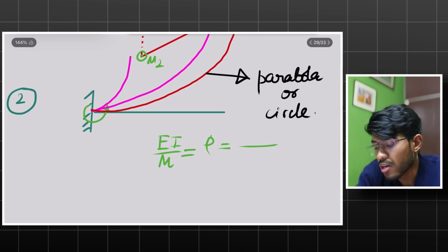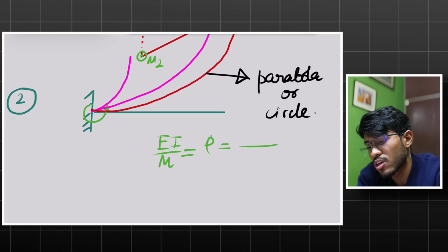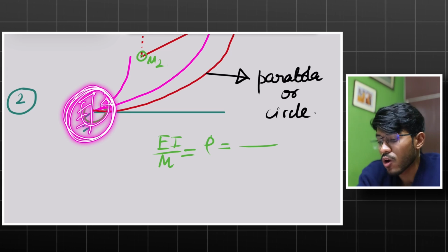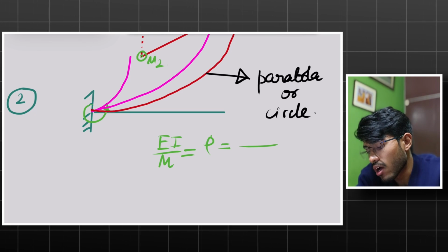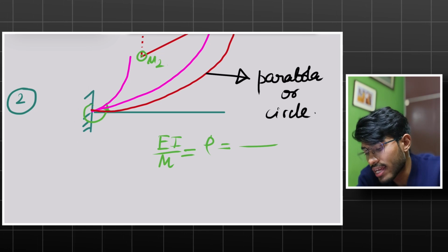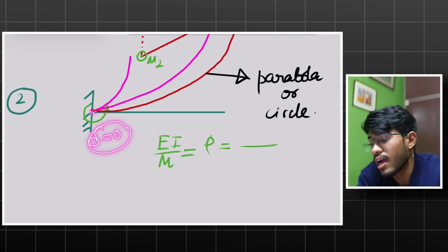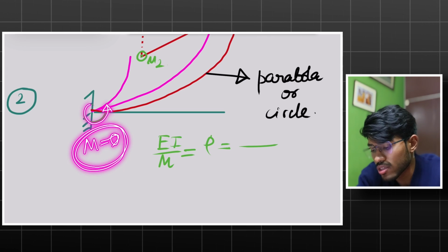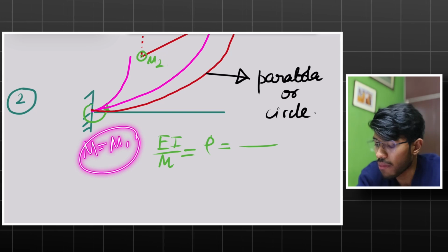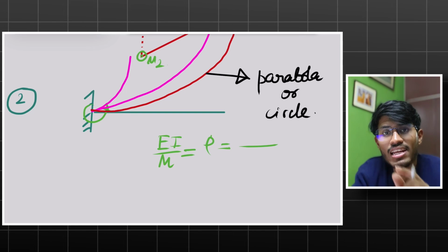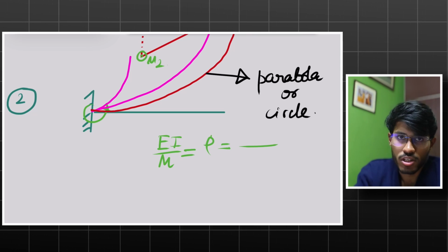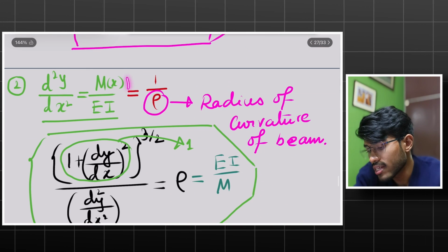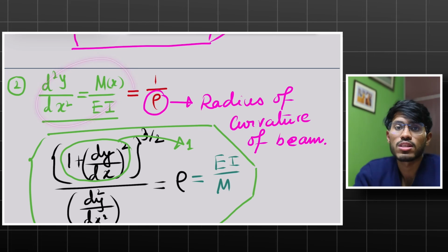Okay, there is one more catch. You cannot apply a fixed support and the moment at the same time, because these two are boundary conditions. When you say it is a fixed support, then the deflection delta will be 0. And when you are giving the moment, then the moment is not 0, it has some value, maybe M1. At any particular point you cannot prescribe two boundary conditions, because you have a second order differential equation, so you need two boundary conditions at two ends.